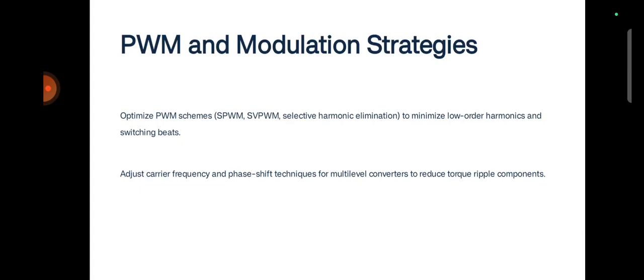PWM modulation strategies. Optimize PWM schemes: PSPWM, SVPWM, selective harmonic elimination to minimize low order harmonics and switching beats. Adjust carrier frequencies and phase shift techniques for multi-level converters to reduce torque ripple components.